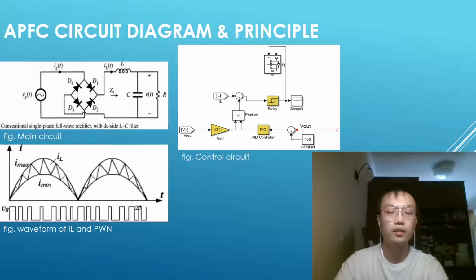The current is still flowing but starts decreasing. The capacitor voltage keeps increasing until the point where the inductor current is below the load current. After a while, the inductor current decreases to zero and the diode turns off. The capacitor continues to be discharged by the load.